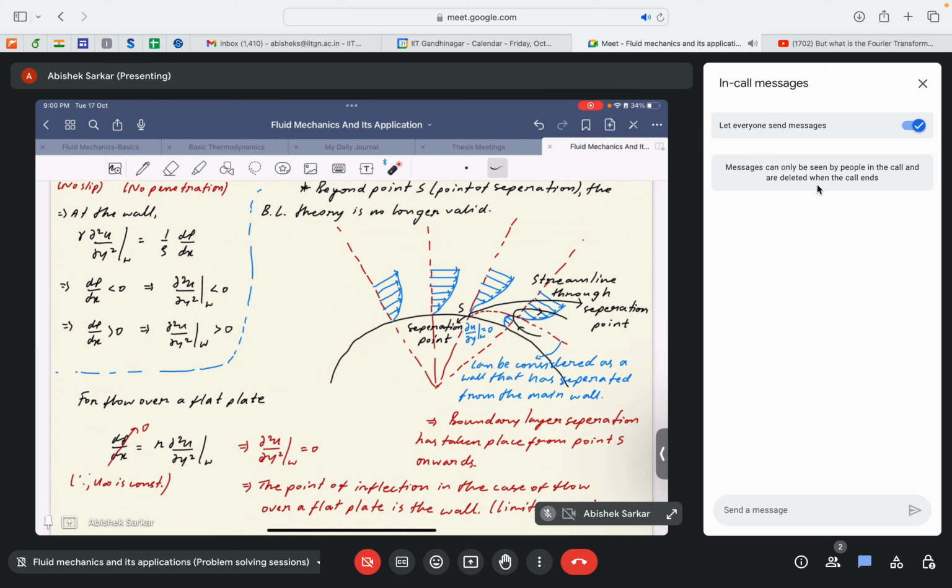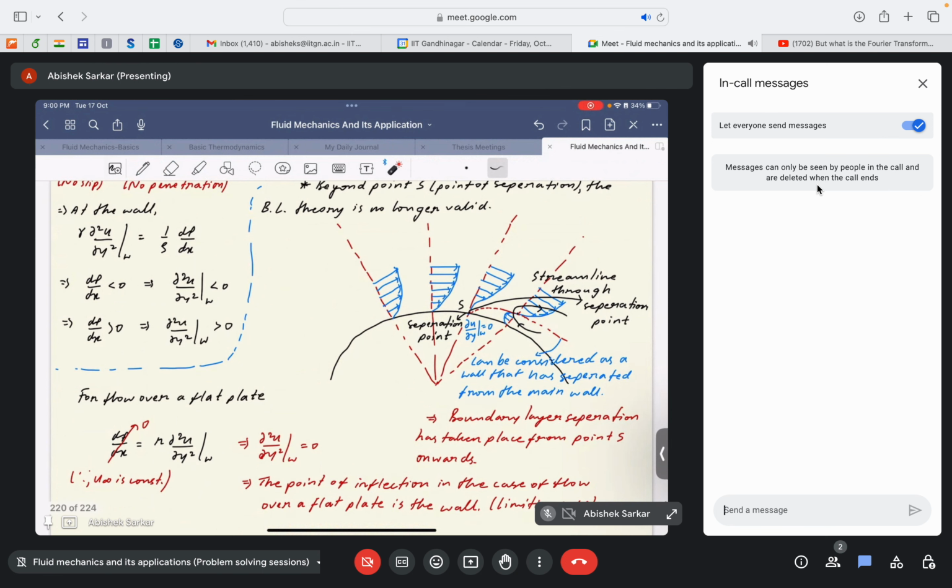These are the velocity profiles at different points in the flow field. You can see here in the first two velocity profiles, the flow is accelerating and is completely attached to the wall. At the third point, the flow is still attached, but it is the onset of separation in the case of this particular shape, right? And at this point, you can see ∂u/∂y at the wall is equal to 0. This is what inherently signifies flow separation.